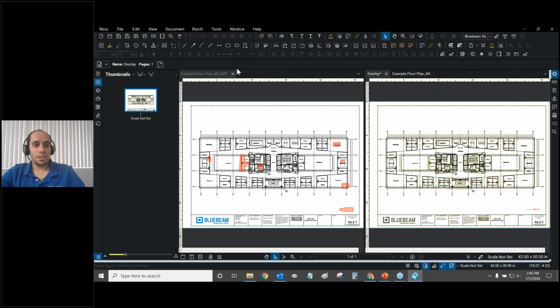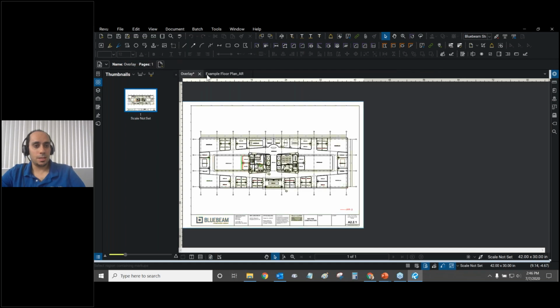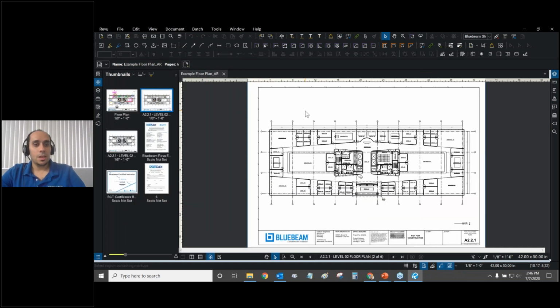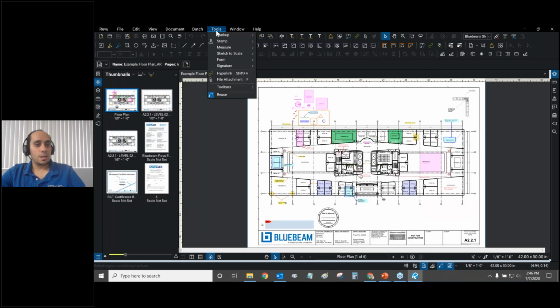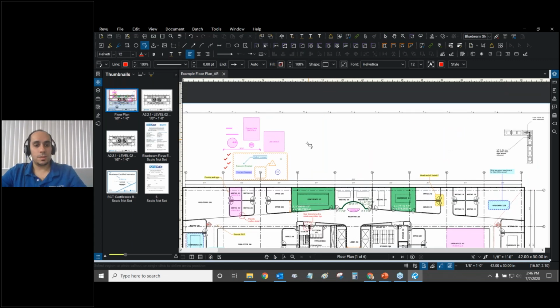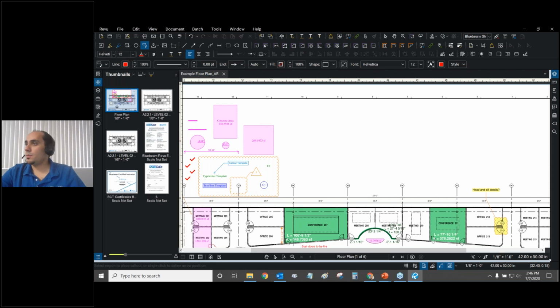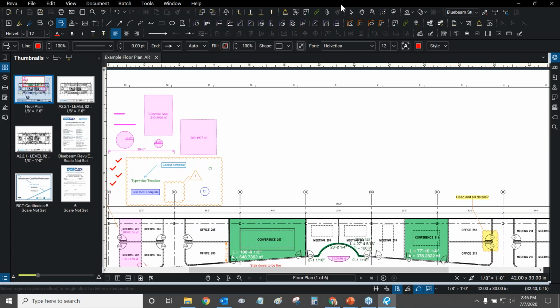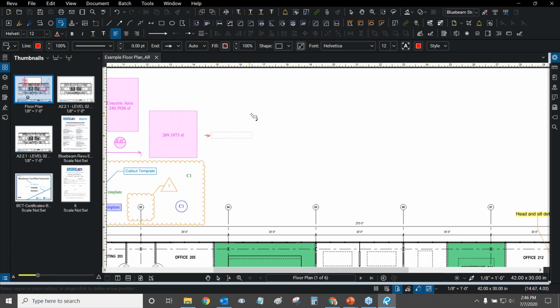So I believe, let's actually get rid of our difference file and let's get rid of our overlay file. So let's try and make a callout. And let's see if we can add more than one leader to this callout. So here, let me get rid of my webcam so you guys can see the majority of my screen. Oops, there we go. Perfect, you guys should see my screen now. Let me actually check. Yes. Okay, so I'm going to make a callout now. So I'm going to point here, move the callout here, type data, my callout is ready.